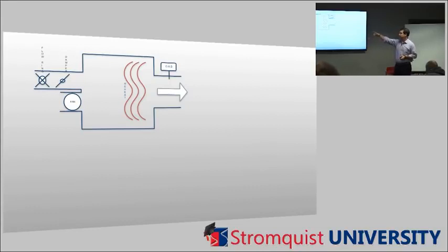And then they actually even have a spot for reheat, so when it calls for heat, you'll see different types of reheat, but this one will be electric reheat. Essentially you've got a little heat strip in there that heats up, and that 55-degree air turns into whatever it needs to be if they need to be heated up in that space, okay? I think it's a 2-day class on VAV boxes. So that's your intro level in 35 seconds. But it's a great class that we teach here if you ever need to know more about VAV boxes.